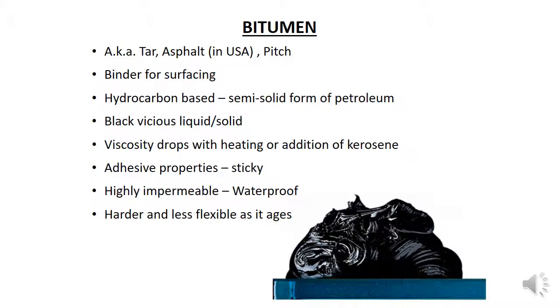Usually, it is heated to around 150 to 180 degrees centigrade. Bitumen starts to burn or ignite at about 230 degrees centigrade, so the working temperatures provide a good safety margin. You can also add less viscous substances, such as kerosene, to lower the viscosity even more, to allow the bitumen to be sprayed over the road as is required for a chip seal, and to soak into the base course as required for a first coat seal. Bitumen with kerosene mixed in is called cutback bitumen.